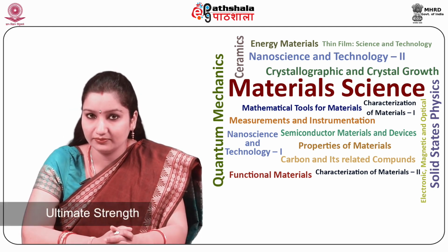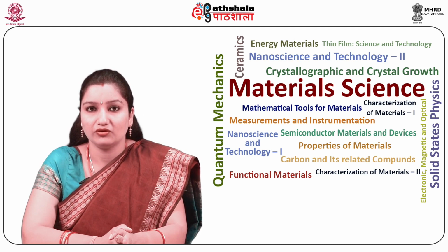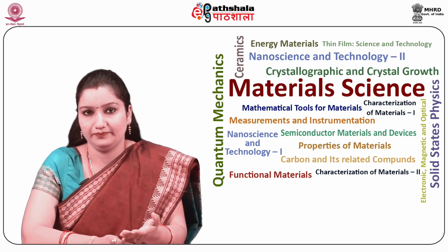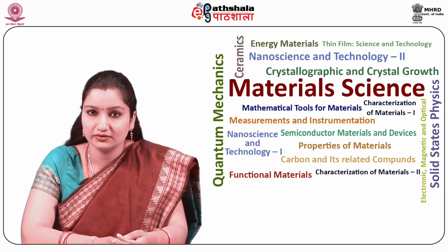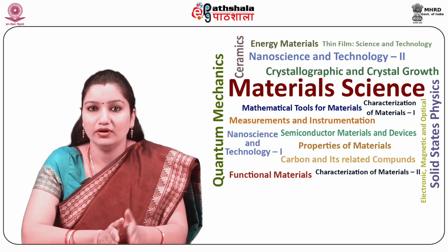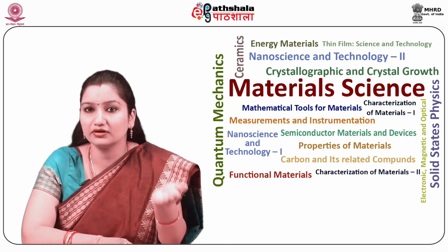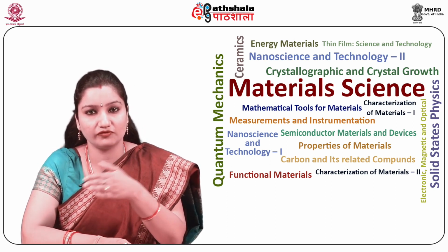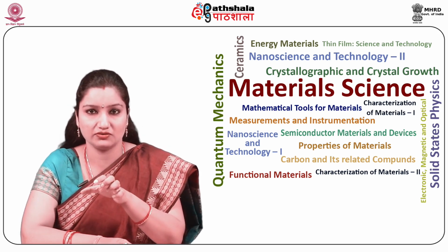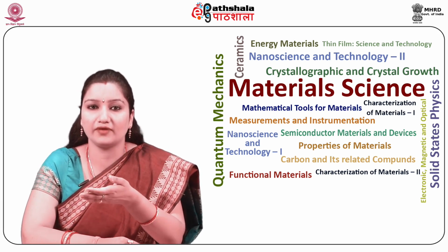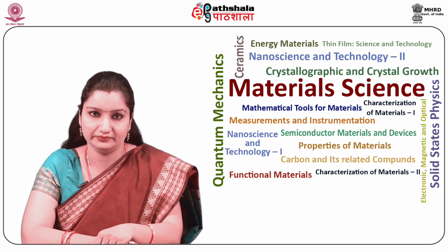First is the ultimate strength. It is the load required to fracture a unit cross section of a material. Then next is the elastic strength. Elastic strength is the value of strength corresponding to transition from elastic to plastic range, that is, when the material changes its behavior from elastic range to plastic range. This is known as ideal stress value and is used to define the elastic strength of a material.